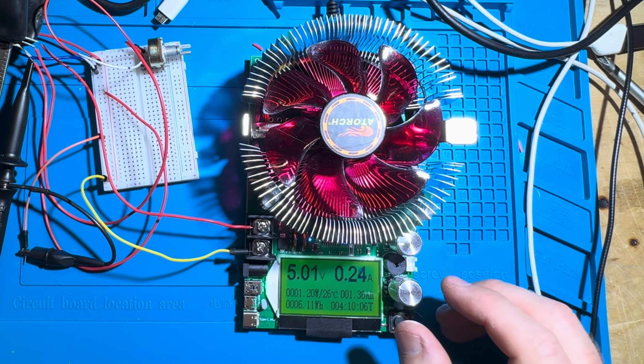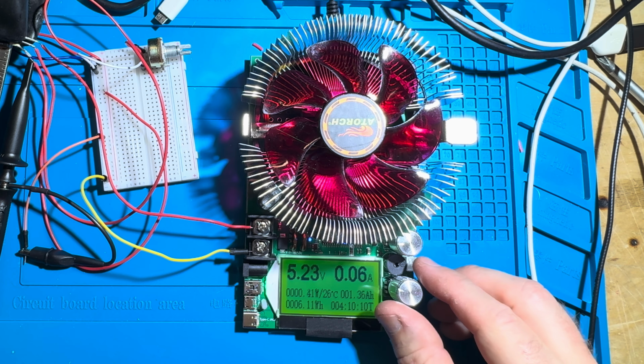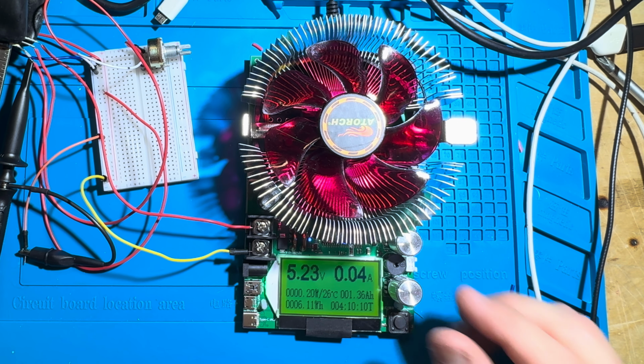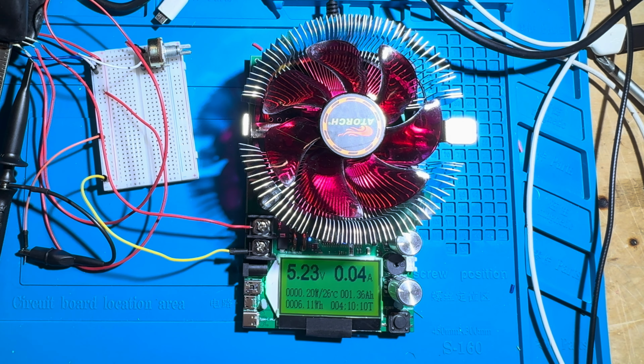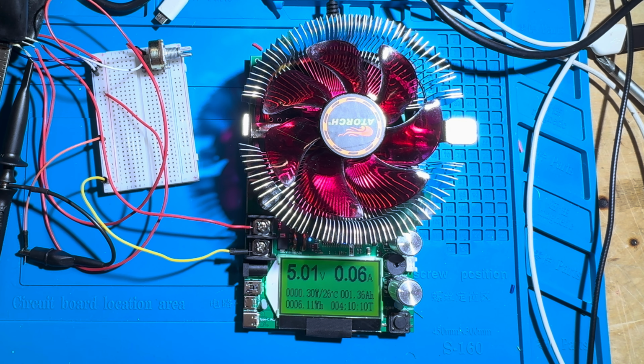If I adjust this load, so if I turn the load way down, say I turn down the volume on my radio and I'm not using nearly as much to produce the amplified output, you see the voltage across our load goes up. So to adapt to that, we need to turn down the gate voltage a little bit more. Oh, that was perfect. To target the 5 volts that we want across this load. So we've got effectively a very janky, adaptable 5 volt power supply, but you can't imagine anybody really using this.